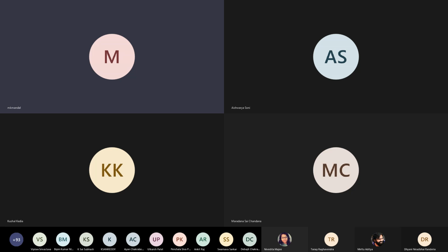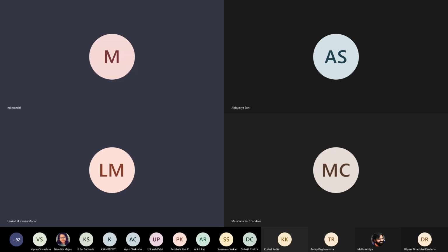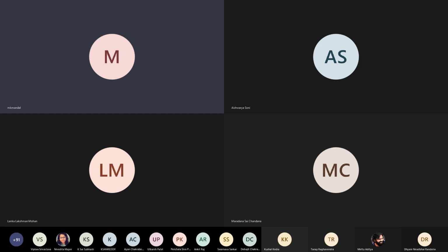If I zoom in on this metal plane, it looks like this. In this case, if I put an imaginary plane just at the middle, you can see the electric field is becoming perpendicular. So then it is a PEC. So this is odd mode excitation of a slot.